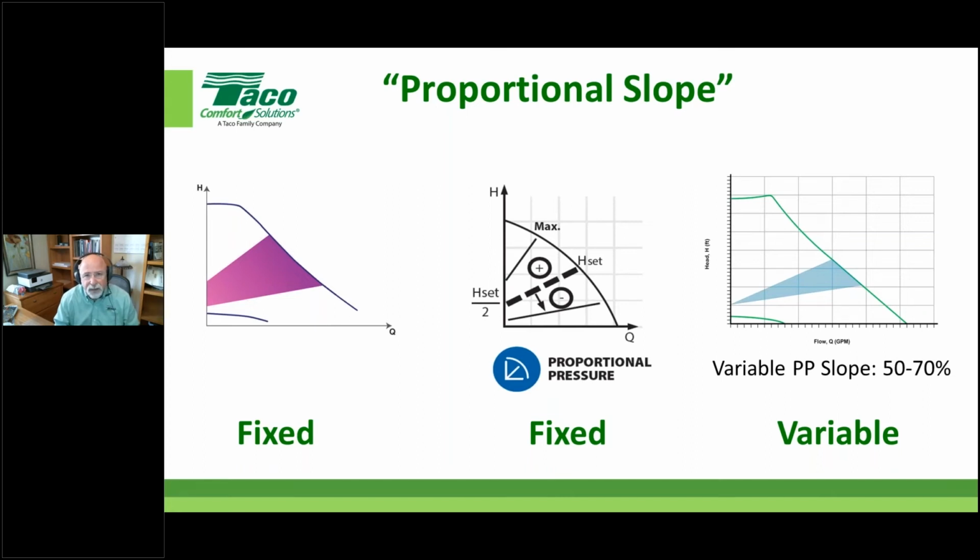Well, let me take a guess at it based on where I think he's going. The balancing is done, and if it's doing automatic balancing, hopefully it was set up under the initial design load condition. And if it's an extended header, and most of those commercial applications will be some sort of extended header, we normally don't have 60 supplies and returns coming back to a mechanical room, but some people would like that. Generally speaking, if it's got an extended header of any sort, the proportional mode of operation is generally the one that works best in those applications.